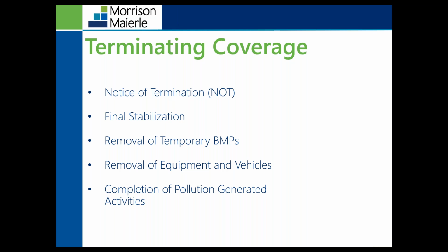So you must submit a notice of termination, or the NOT, to DEQ. You are eligible to terminate your coverage once you've reached final stabilization, which is when vegetation has reached 70% of the existing density prior to construction.